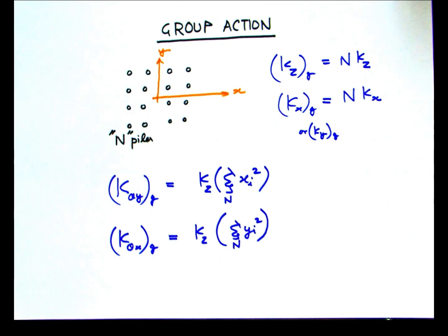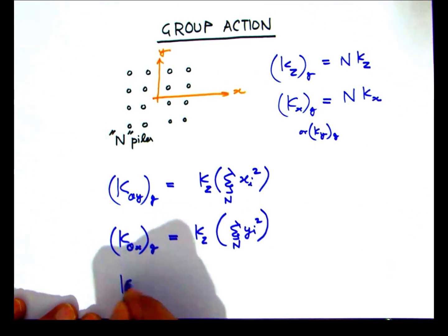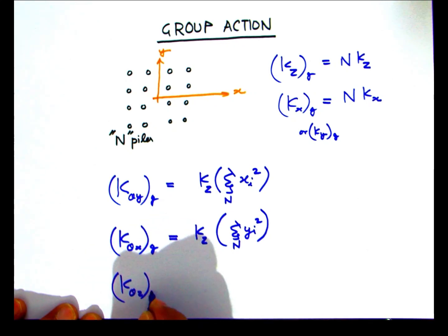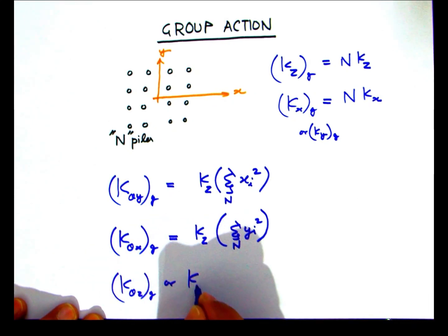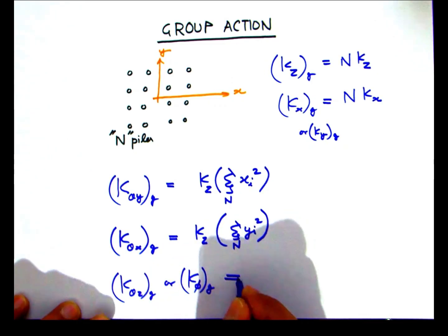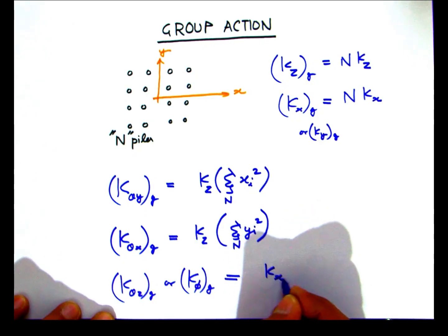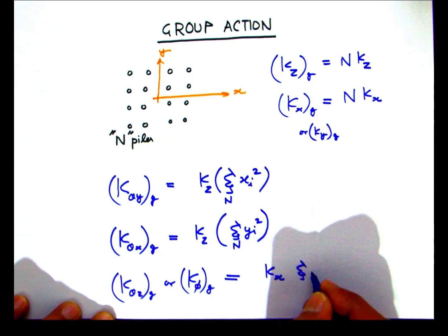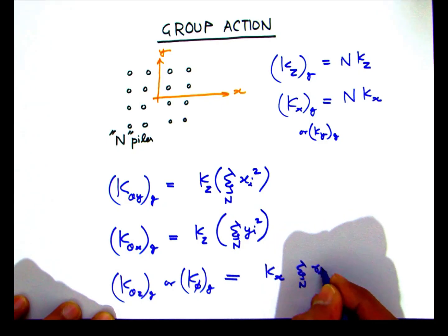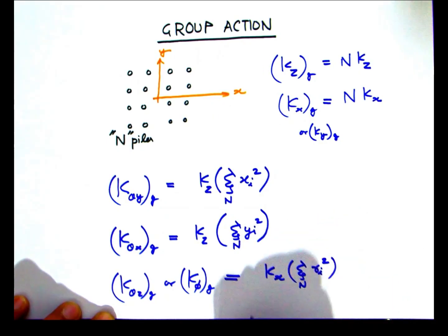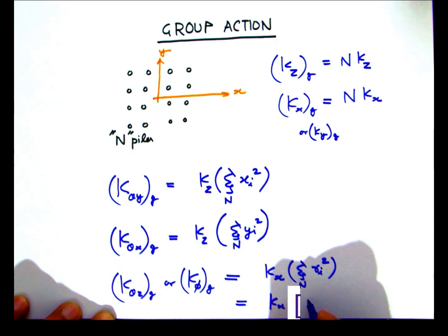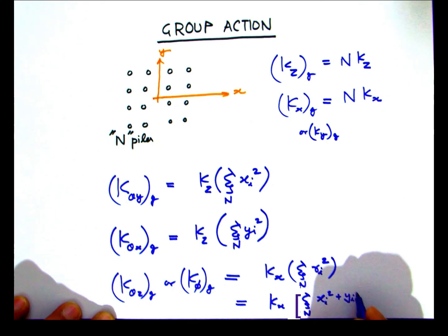Now finally, for the group stiffness about the z-axis, that is the torsion, which is also denoted by k phi or k xi, that depends on the horizontal stiffness. So what we have done is we have multiplied with the sum of squares of the radial distances of the centers of the piles from the overall CG of the system in plan, and this can also be written in terms of xi square plus yi square covering all the piles.